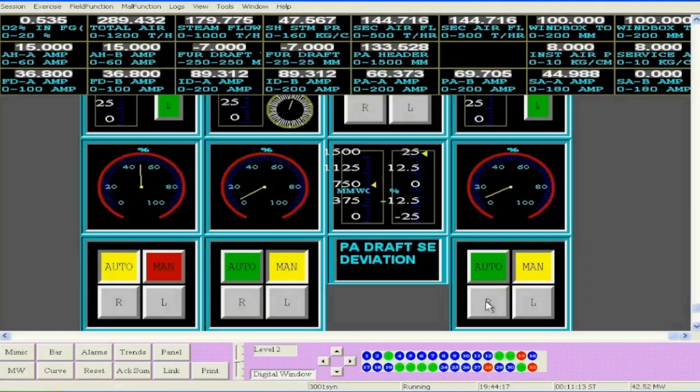When we increase this header pressure, we will keep in mind that the flow is very little, or maybe whatever is the leakage, maybe we have opened the cold air damper also. So through the mill, maybe the cold air is passing only through the feeder, through the coal mill, but the mill is not running.